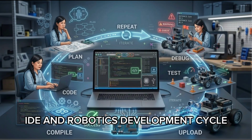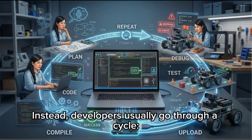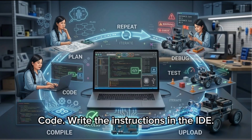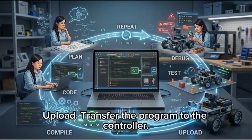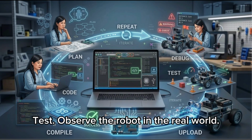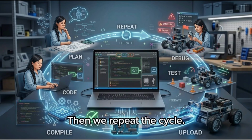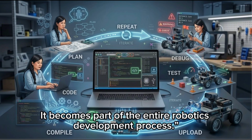IDE and robotics development cycle. Robotics programming is rarely a one-click process. Instead, developers usually go through a cycle. Plan: decide what the robot should do. Code: write the instructions in the IDE. Compile: check whether the program can be built successfully. Upload: transfer the program to the controller. Test: observe the robot in the real world. Debug: find and correct problems. Then we repeat the cycle. This is why an IDE is not simply a writing tool. It becomes part of the entire robotics development process.